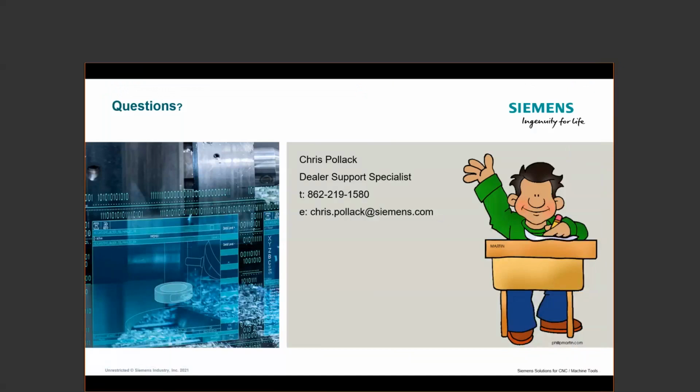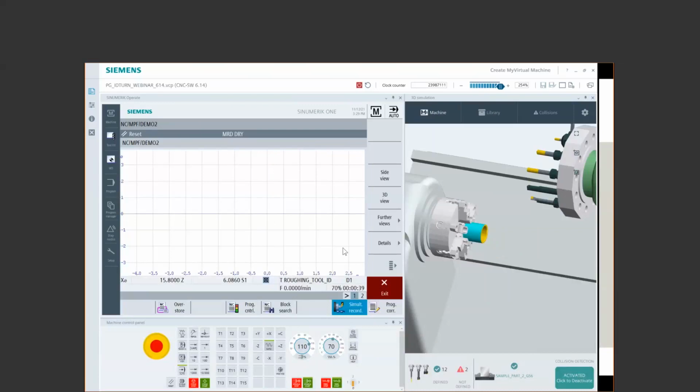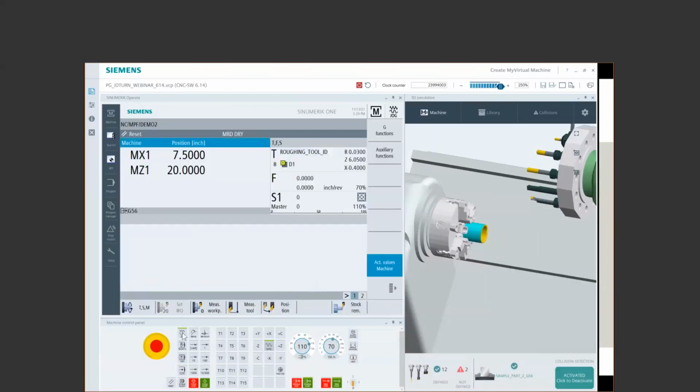Do you turn off diameter mode at the end of the program? No, not typically in a lathe. Typically in a lathe, I usually always leave the machine with diameter mode on. In fact, the system is probably set up by the OEM to be always on diameter mode on. An easy way to see how your system has been pre-configured: do it in jog or in auto, but you want to be sitting in a reset state.